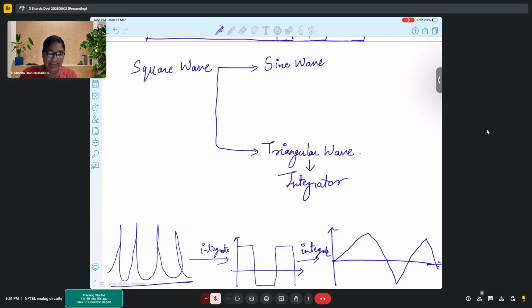Yes, bandpass filter? Yes. We can have a bandpass filter with very high Q and low bandwidth, such that it only passes a single frequency. If it only passes a single frequency, then that bandpass filter can be used to extract a single sine wave out of the multiple sine waves present in a square wave. Okay, so we can do bandpass filtering